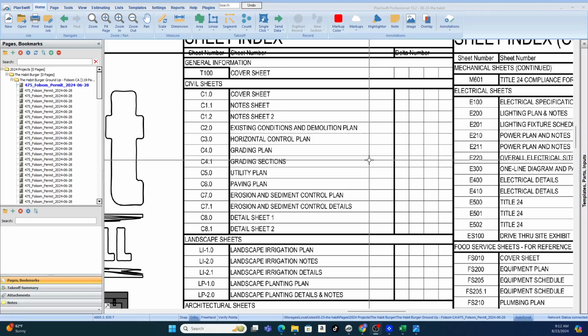And so when you think about the civil set, we have to move dirt, we have to excavate, right? When you have a project with a C set of plans, it's almost certain it's from the ground up. Because if we have a civil set, that means we have a utility plan, meaning we have underground water, gas, sewer, storm that has to be built. Okay. And so those are the plans that you have.